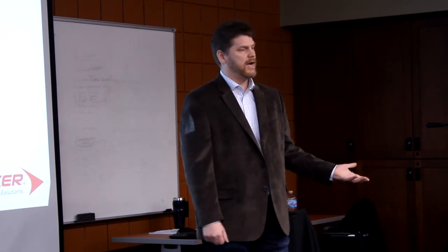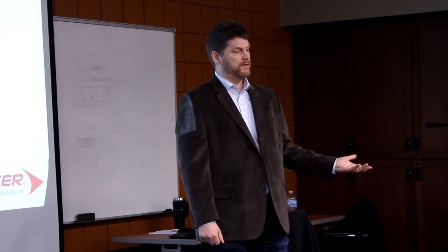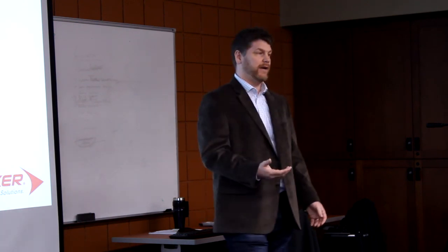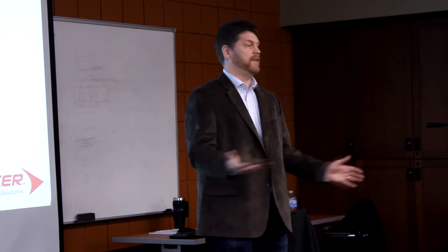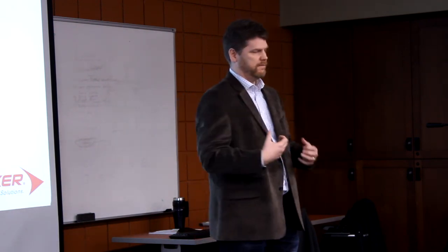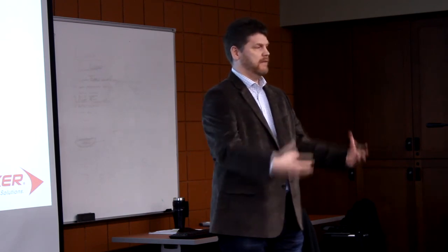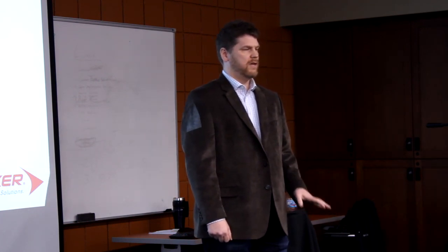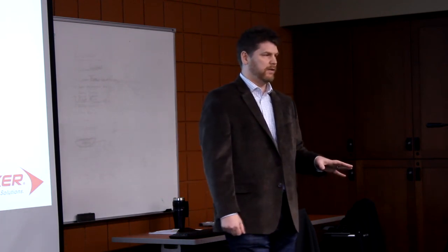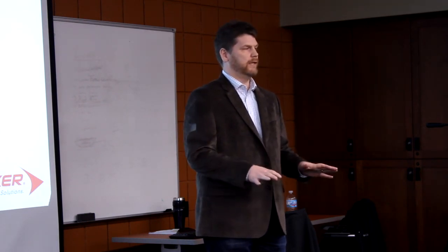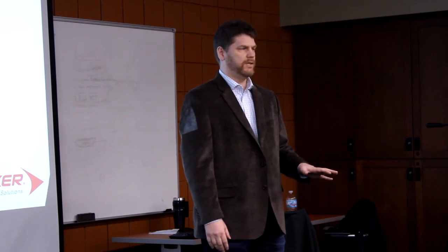Where they are efficiency-wise, they are not quite as efficient as InGaN. For instance, the efficiency of a blue InGaN die nowadays is almost more than 50%, which to me is amazing. You get at least 50% of the energy that you put into an LED out as light. That's pretty awesome. OLEDs are almost there, but not quite. The other difficulty with OLEDs is that they are hydrocarbon based, and if they're penetrated by oxygen molecules, or in general water, they tend to degrade rapidly. So encapsulation with OLEDs is the huge issue.